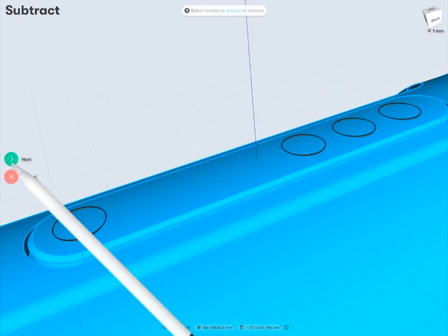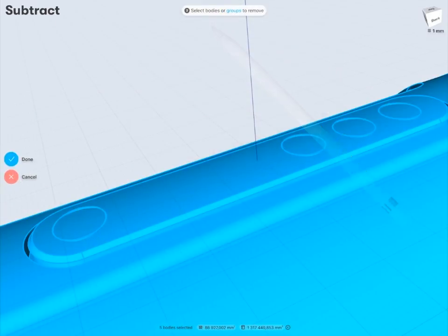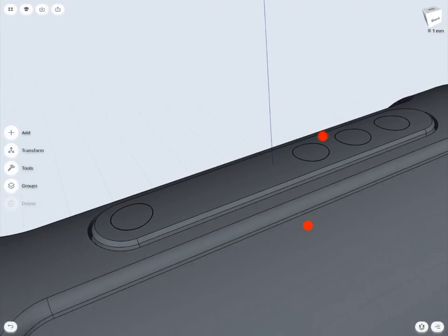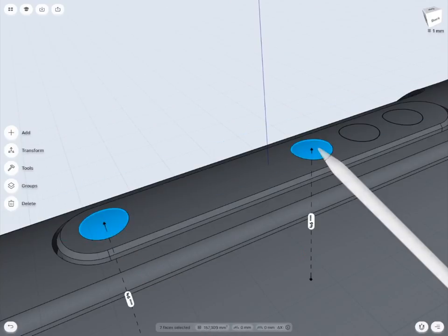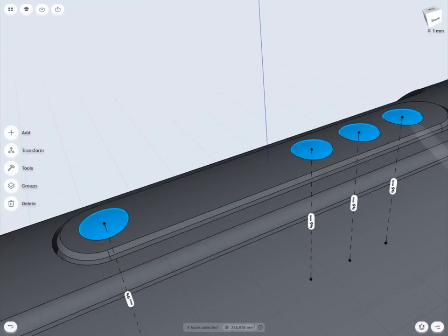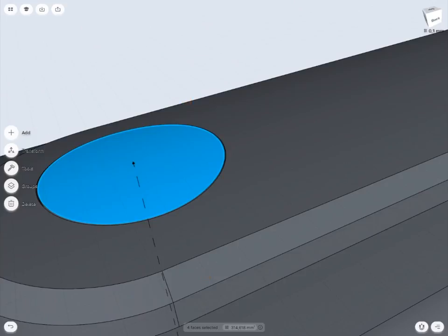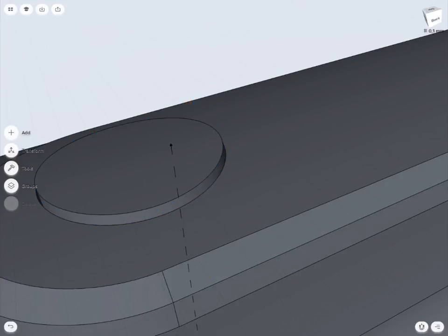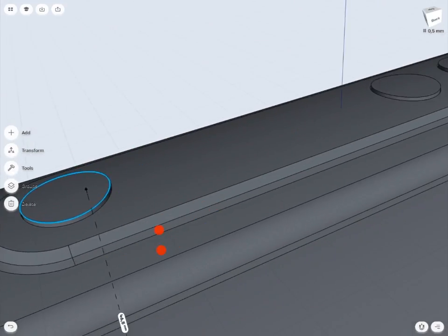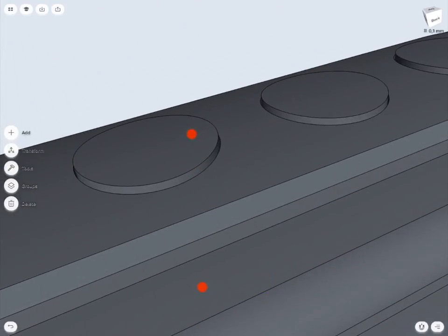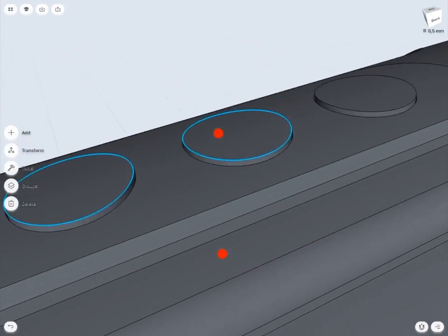I'm going to cut where needed using the Group Cut tool, which is the group that contains any cutting bodies. And now if you get closer, you'll see what I've done. It's a small gap between the button and the top bar. Now I'm going to select the edges of the buttons and make a fillet.